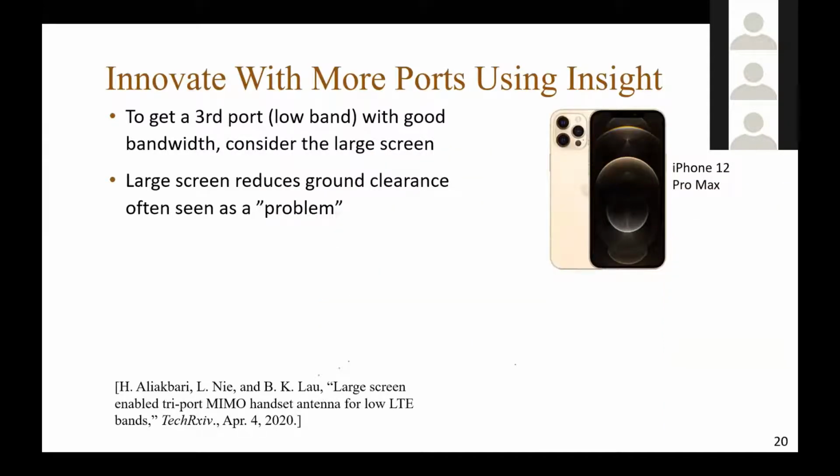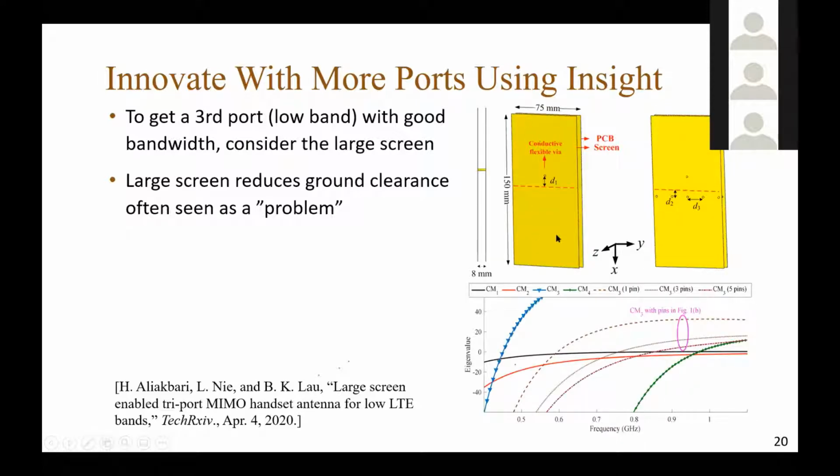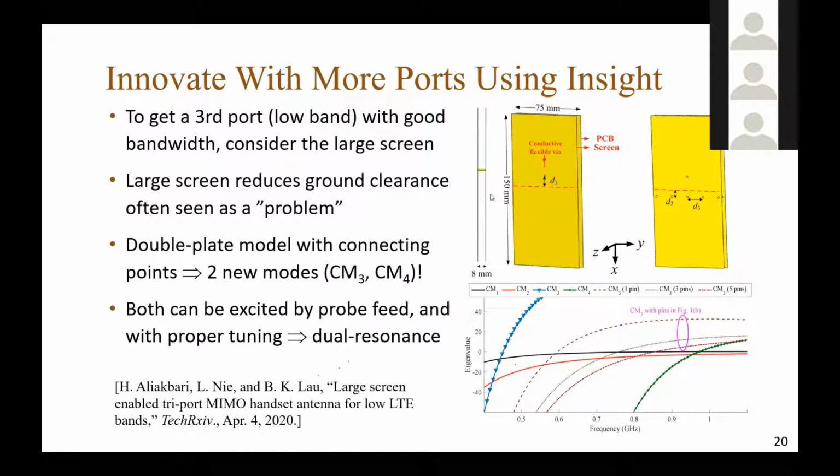We want to have more ports, and how do we do that? We can, again, go back to characteristic mode analysis to look at what is contributed by the screen, which is traditionally seen as a problem. If we take into account the screen, which can be modeled by a metal plate, say a 2-plate structure with some shorting pins between the plates, we find that we have 2 new modes that are created by this 2-plate structure with